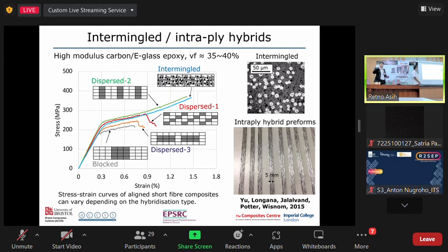So basically, the choice of what level and what type of structural health monitoring complexity you put in depends on what you need from the monitoring system. Is it just to give you an early warning that you need to replace something, or is it to give you more information, such as the effect of a defect on the overall performance of the structure? If that's the case, then you need more data.